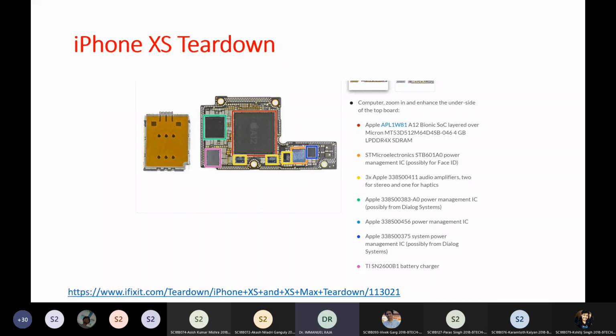or for that matter most of your Android phones, you will have this Qualcomm Snapdragon processor or whatever it is, right? Now, there is what is called dynamic voltage and frequency scaling. That's a big term. To put it very briefly, in digital ICs, power is very much tied to the frequency of operation. If your clock rate is high, if you're crunching numbers at a higher speed, you will have more power dissipation, because for an inverter, the power dissipation is alpha times C V squared F, right? So as F, the frequency of operation, your clock frequency, increases, your power will also increase.